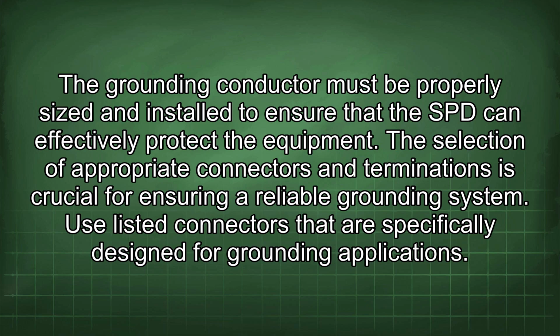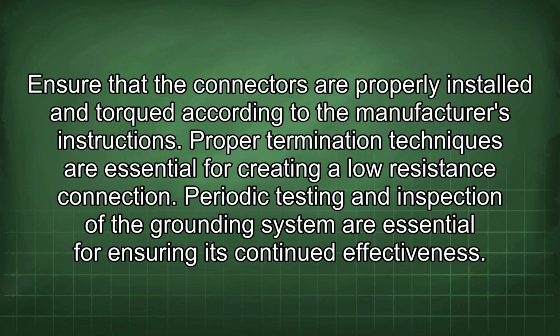The selection of appropriate connectors and terminations is crucial for ensuring a reliable grounding system. Use listed connectors that are specifically designed for grounding applications. Ensure that the connectors are properly installed and torqued according to the manufacturer's instructions. Proper termination techniques are essential for creating a low-resistance connection.